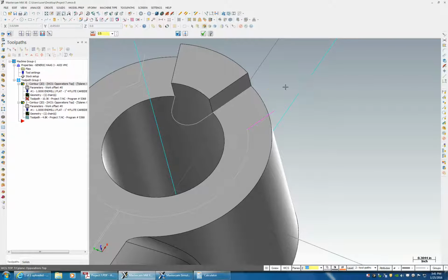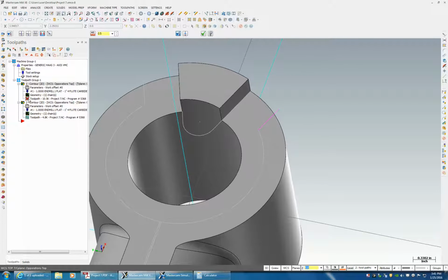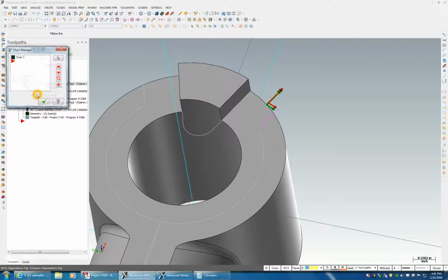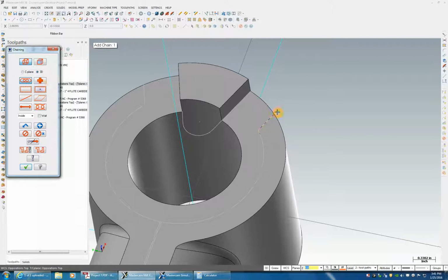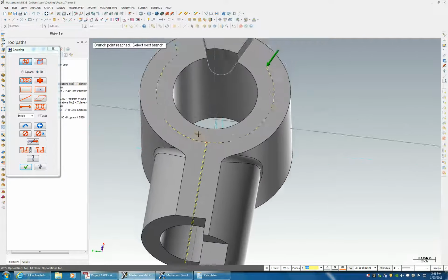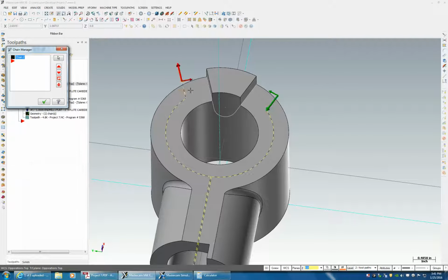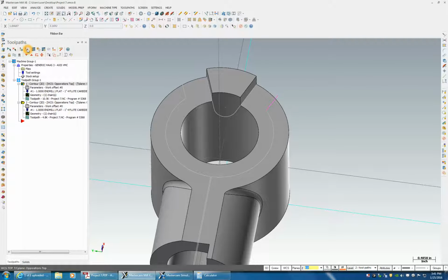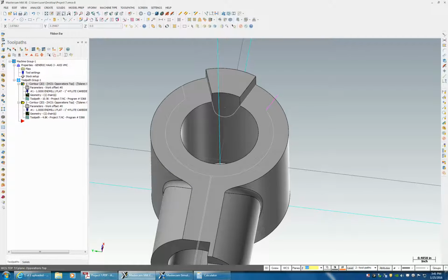It didn't. But see how the toolpath is now dirty here? We've got to come back and reselect our geometry. So rechain all, starting here, coming around, down here, back around, and up to there. The cutter comp really doesn't matter on this one because we're not compensating. Now let's go take a look at our simulation.